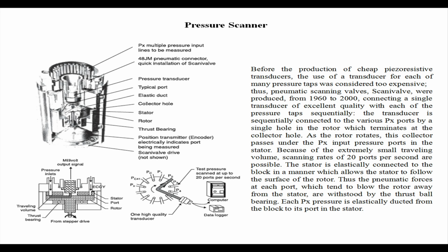By the time it rotates to another port, you see no signal, and then it moves on to this port, engages, and again it sees a signal. So, there would be some pressure, a gap, some other pressure, another gap, and that is the way it used to go on. And then there would have to be very good machining done so that there is no pressure leakage, because you have a rotor and a stator there engaging with each other.